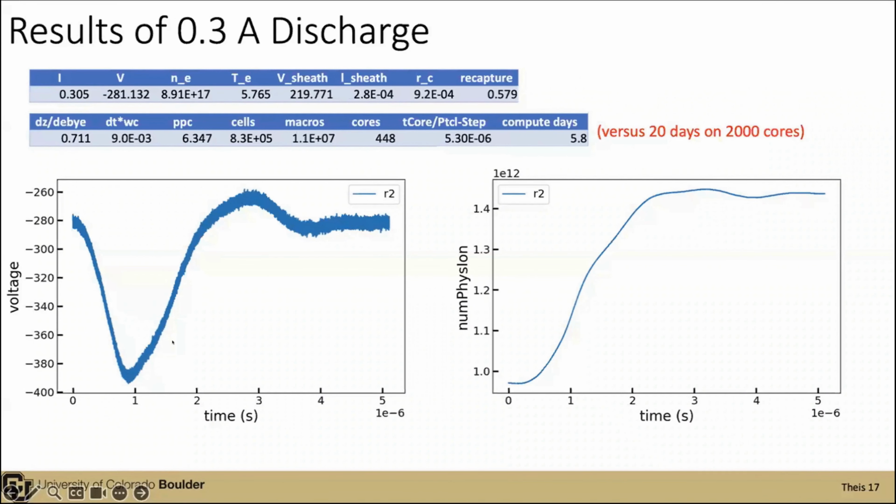And this plot on the bottom left shows the voltage of the cathode as a function of time. I restarted this from a lower current, and that's a technique I've been using as well. So I restart from a steady state achieved at a lower current for my next simulation. And then I do a time-dependent resistance, which basically ramps that resistance down to the next resistance I want to simulate, if you remember my external resistance plot from before. And then I allow it to evolve freely at that constant resistance, in which case I get a little bit of overshoot, but the ringing settles down really quickly before I get the steady state voltage. It doesn't look totally clear that it's a steady state on this voltage plot, but if you look at the number of ions, it's a bit more clear that there's this rise time and then some ringing, but we're in the steady state regime.